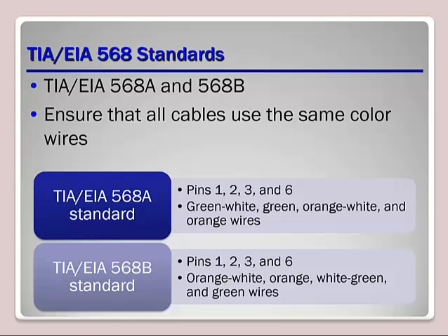Okay. All right, so this brings us into the TIA/EIA 568 standards. I'm just going to keep saying that, but it's the 568A and B. And all there is to these standards is the way that you wire the cables into the jacks and onto the modular ports. So what does that mean?